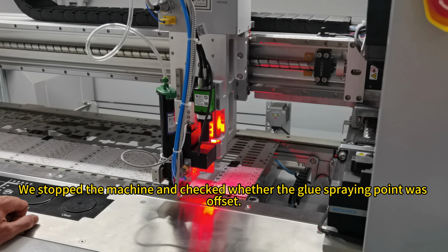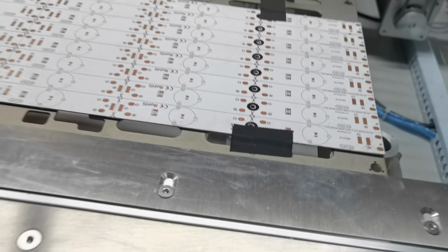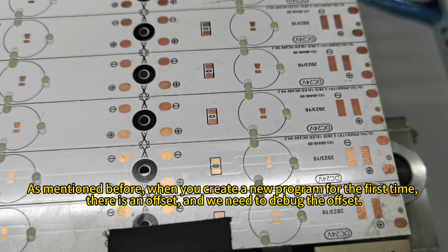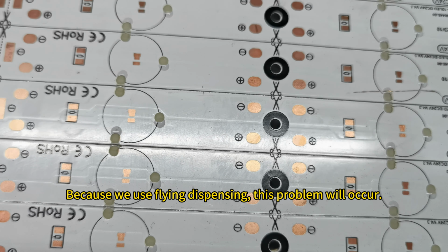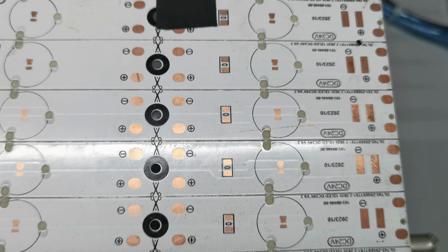We stopped the machine and checked whether the glue spraying point was offset. As mentioned before, when you create a new program for the first time, there is an offset and we need to debug the offset. Because we use flying dispensing, this problem will occur.